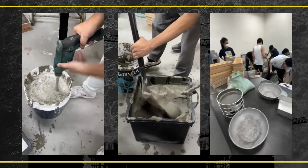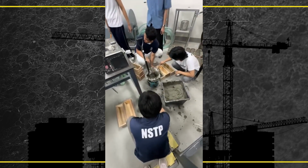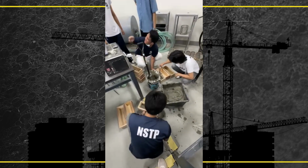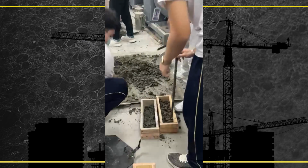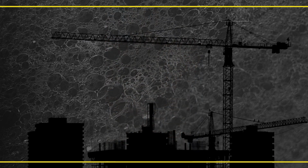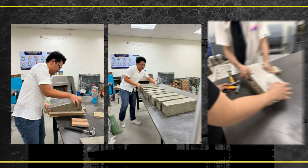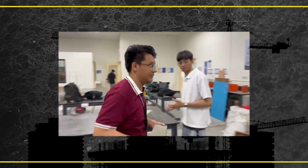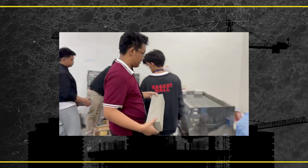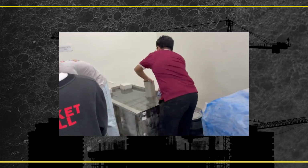Once the mixture reached the desired consistency, it was placed into the prepared wooden molds. During casting, the mixture was carefully poured and subjected to tamping and light hammering to reduce large voids while preserving foam stability. The specimens were then left inside the molds for 24 hours to allow initial setting before demolding. After demolding, the samples were cured for 7 days, 15 days, and 29 days, allowing sufficient time for strength development.